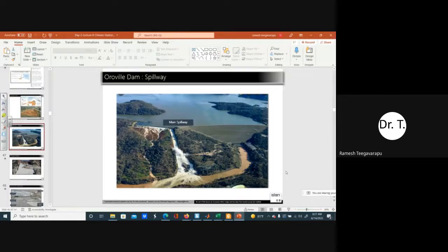If you have enough confidence, then you can do a controlled release of water, and that's what many countries do, including Japan, and even the United States now is doing what we call a controlled release, so that the downstream channel capacities are never exceeded. So you release the water slowly over a 10-day period and create that extra storage that might be needed for the extreme rainfall event. So it's more of a preemptive action.